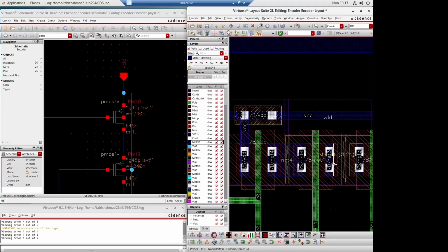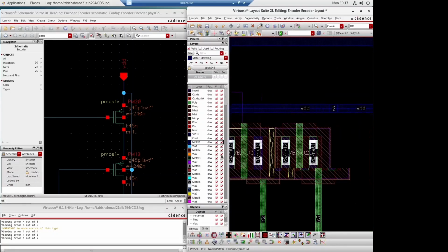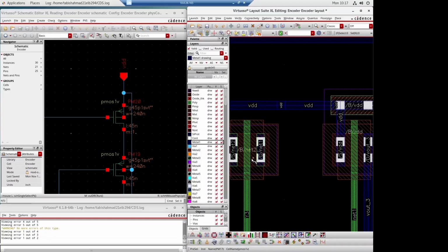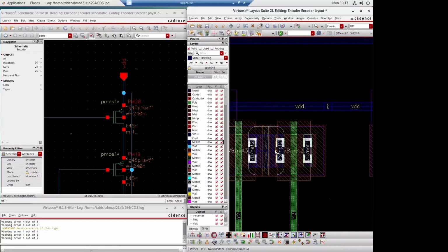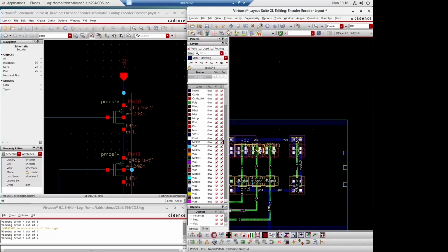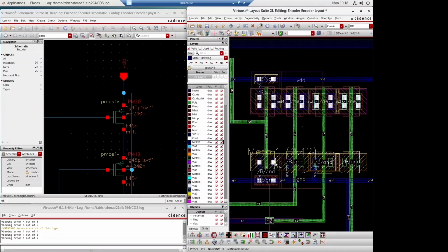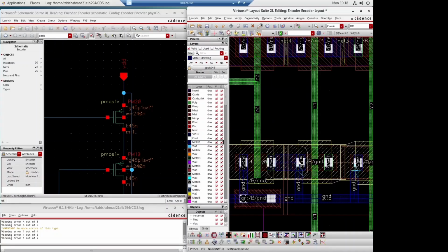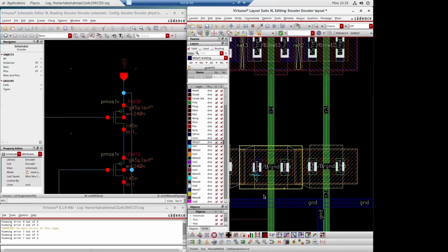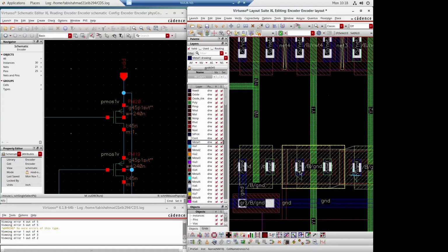Connected with new wire, new metal line. In NMOS also the metal lines were not connected, so that was the error. We will connect them now, and these shifted ground lines should also be removed. Old connections should be removed. We'll connect new connections. This with the left one.